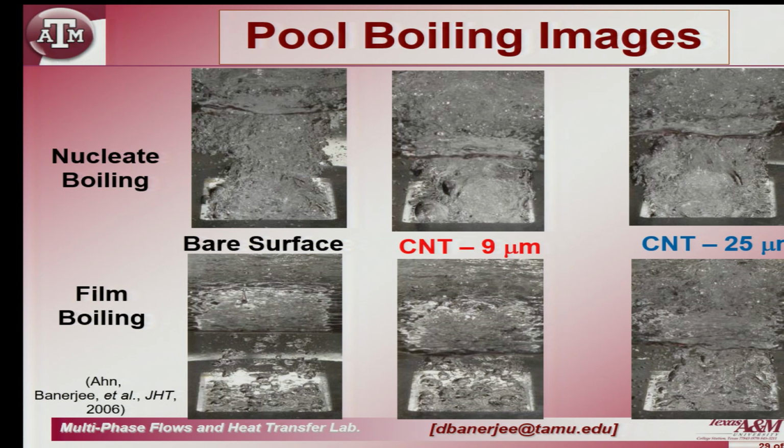because of what that does, and not just any nanotubes, but nanotubes that are thicker than the vapor film thickness. So, what my CFD model was telling me was that I get the bubble with different thicknesses of the vapor film, right, that vapor blanket. At the point where you have the minimum vapor film thickness, my computer model was predicting that it was about 15 microns thick.